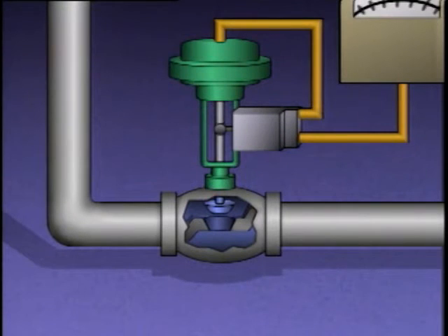If we move the positioner to one side, we can see that a mechanical linkage joins the valve stem to the positioner. This linkage, often called the feedback linkage, indicates the valve's position to the positioner. The output speed from a single speed motor can be controlled by connecting it to the process through a variable speed coupling. In this case, the coupling acts as the final control element.